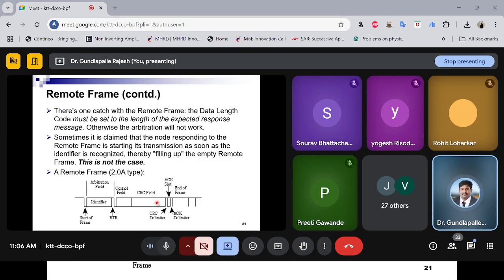Most of the time these remote frames will be sent empty, because there won't be much control required. Let us take an example in an automatic car. If you press a button to close the window, it doesn't require any feedback, it just goes and closes. But suppose an obstacle comes during closing. It has to stop, otherwise the obstacle will also be pushed up, and if it is a human hand, it will get damaged. At that time we require feedback, isn't it?